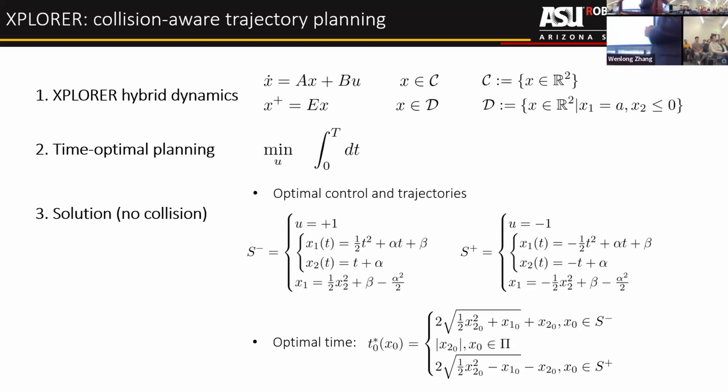So I'm listing a sketch of the controller design here, but a couple of things to note without going into every detail. The first one is we need to understand that the drone now has hybrid dynamics, right? Which means when the drone collides into the environment, you're going to see an instantaneous change of the velocity. It flies in at, for example, 3 meters per second, and then when it bounces back, it's going to be like -1, -2, depending on what people usually call the coefficient of restitution, right? Of course, that is a very important environment parameter that we have to identify. But we need to understand there is hybrid dynamics.